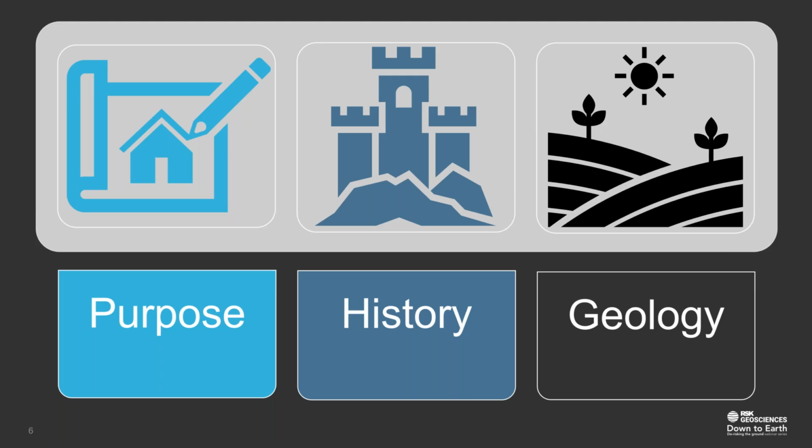This would be your housing or high-rise residential. Category 3 are structures or part of structures which fall outside of the limits of categories 1 and 2. Examples of this are very large or unusual structures, or structures involving abnormal risks or unusually or exceptionally difficult ground conditions, or perhaps unusual loading conditions. Structures in highly seismic areas, or structures in areas of probable site instability or persistent ground movements are also going to be put into this category.